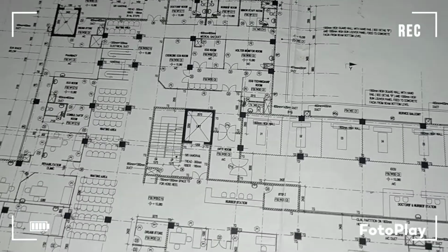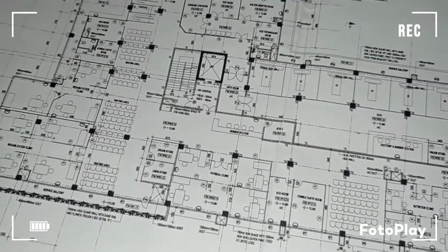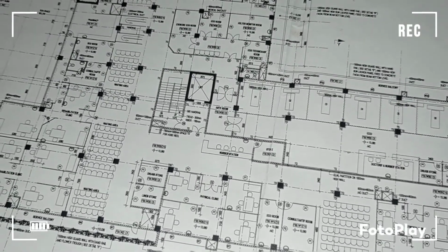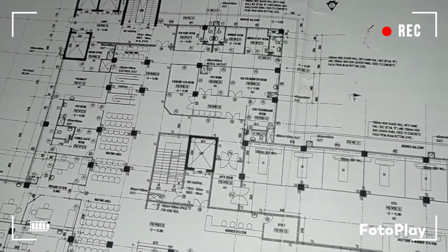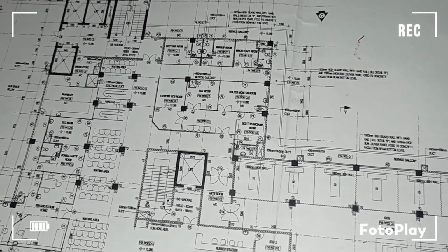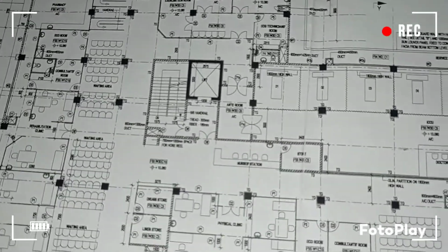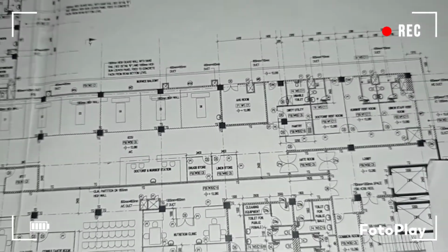We have to decide a suitable beam arrangement for this, primary beams as well as secondary beams, and column places. If these are good enough to carry or transfer the loads effectively, we can keep them. If we need additional columns, we have to place them. If we have additional columns in the architectural drawing, we can remove them.